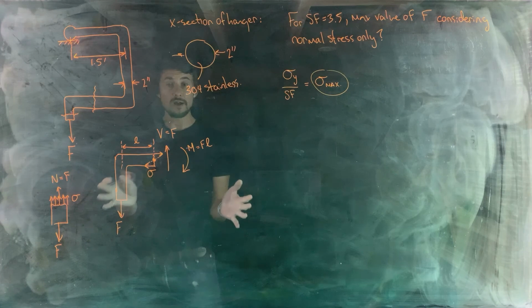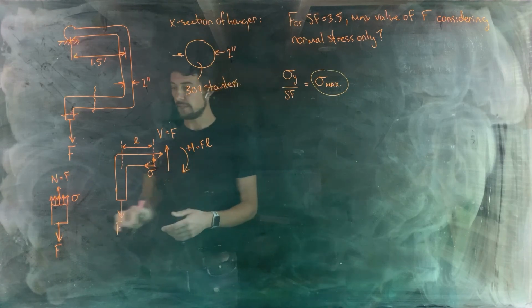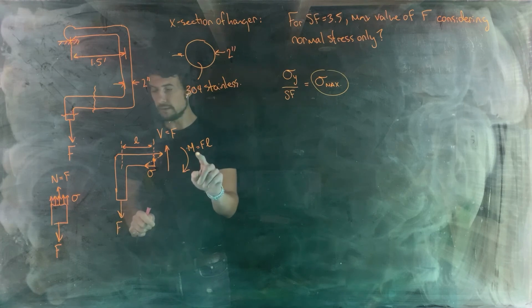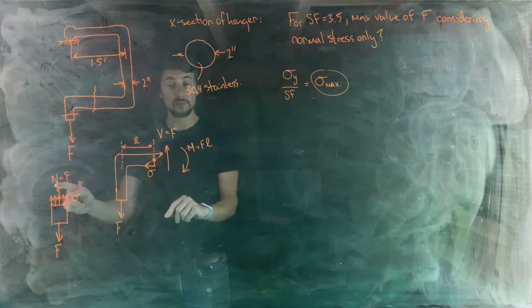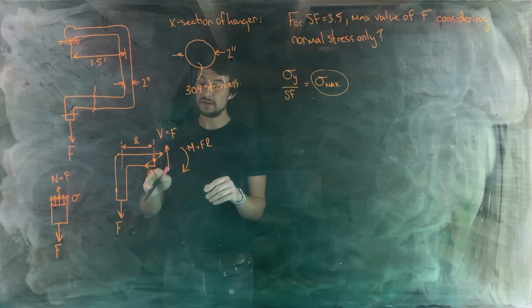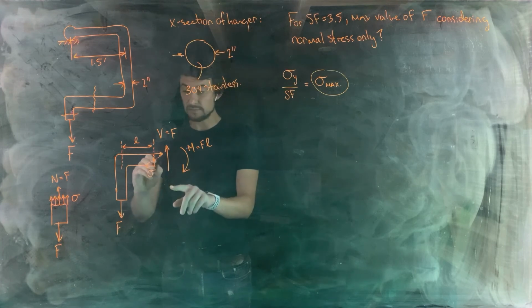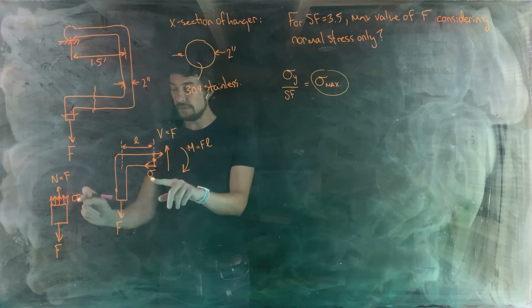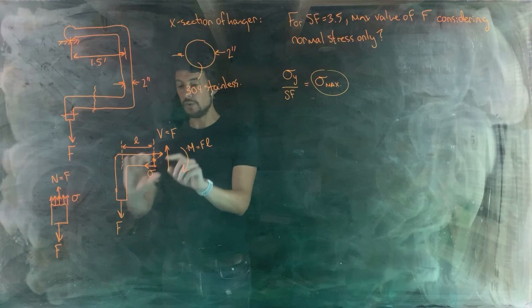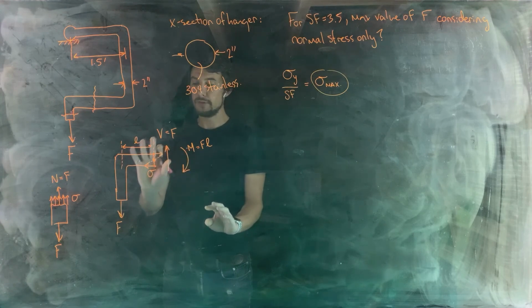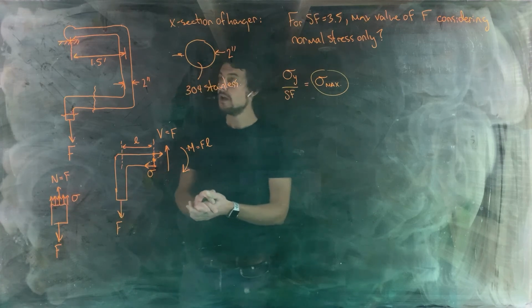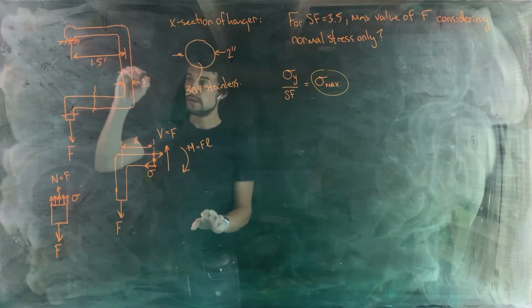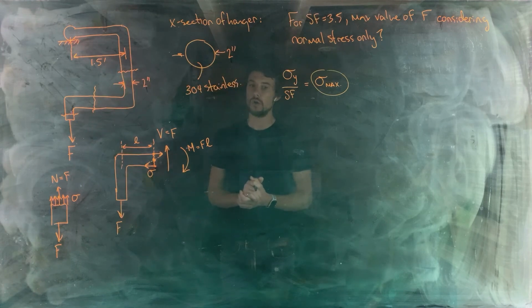We know from doing our calculations throughout the course that normal stress due to bending moments tend to be larger than normal stress due to internal normal forces. So there's a very good chance that this normal stress here, or the maximum normal stress, which would occur at the edges, is significantly greater than the normal stress created from the normal force. So this is a better location to look for the maximum normal stress than this location over here. So let's keep going. What if we cut somewhere like that?